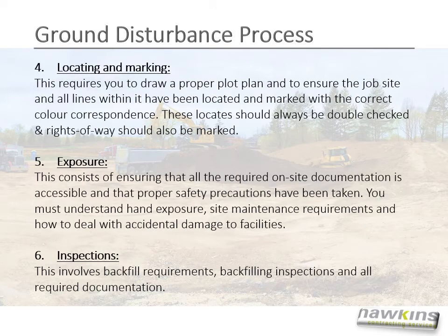Step 4 in the process is locating and marking. This requires you to draw a proper plot plan and to ensure the job site and all lines within it have been located and marked with the correct color correspondence. These locates should always be double checked and rights of way should also be marked.